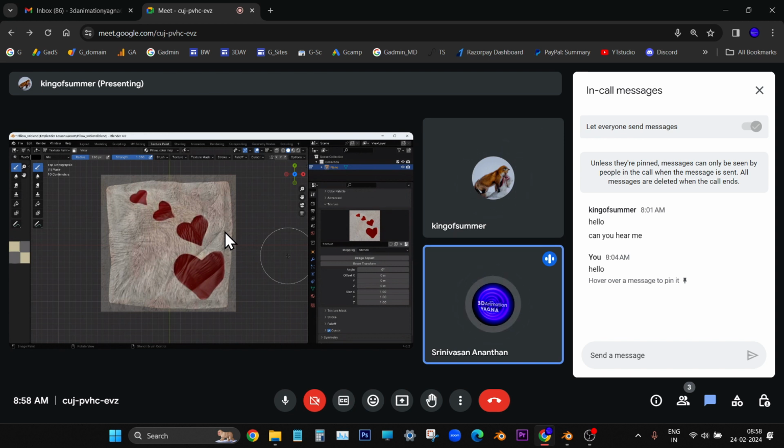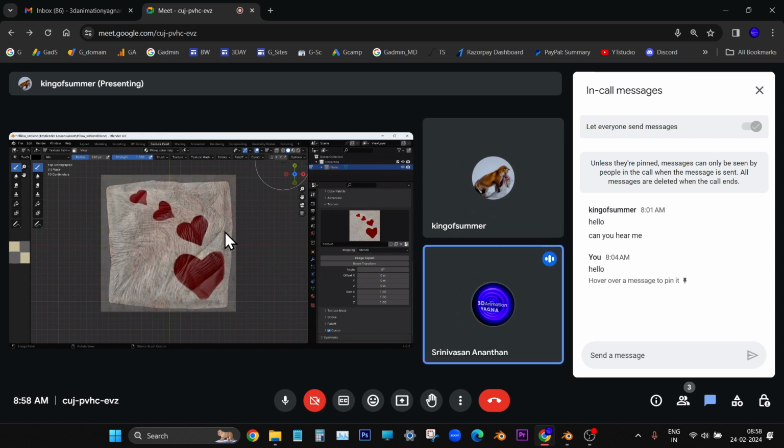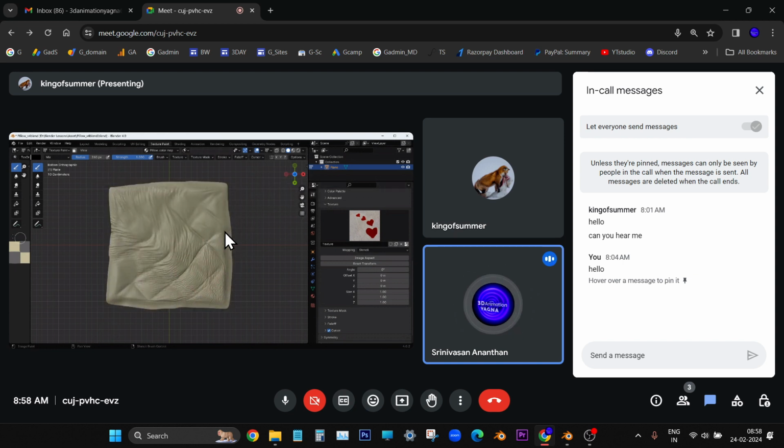Now, do you see the gizmo on the right side, the big XYZ global gizmo on the viewport? Just press exactly on Z. Now you know what has happened. It is in minus Z, right? Take your cursor to the left side. Bottom orthographic it is showing, right? It was top orthographic, now it is bottom orthographic.